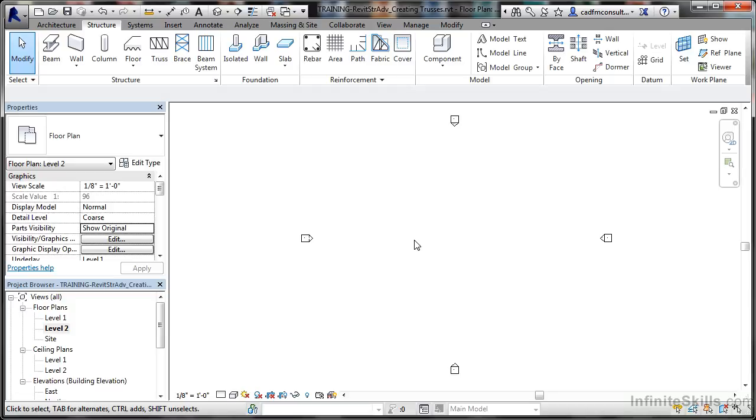So what is a truss? What does it do? A truss is comprised of one or more triangular sections. Now, when I say sections, I mean areas of a frame, not actual steelwork sections like a beam or a column. However, it is made up from steel beams. These sections are constructed with structural members, and these ends are connected at joints, which are referred to in Revit as nodes. And as forces act on these nodes, the triangular shape of the truss provides that structural stability to stop the truss from bending.